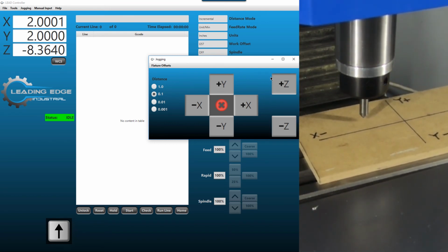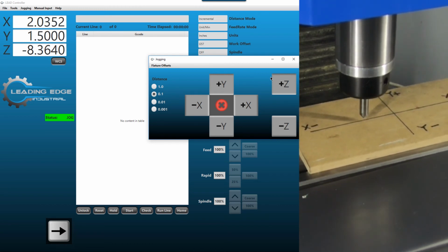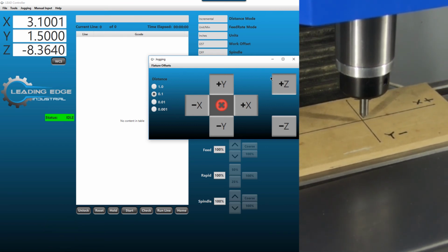I like to do the center of the workpiece because if there's any variance in the sheet thickness, and the same thing along the edge, especially when you're doing a quick set off like this, if you touch off on any of the edges there, then it'll compensate for any kind of miss setup, whether it's slightly cockeyed or whatever. But also, if you set off at the center of the sheet, ideally you're hitting at the center of the most positive and negative portion of that workpiece. So now we're over here in the middle.